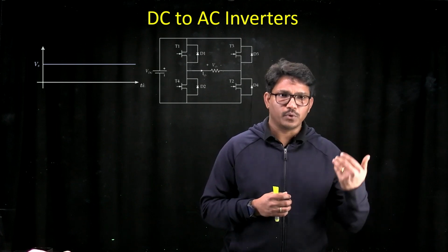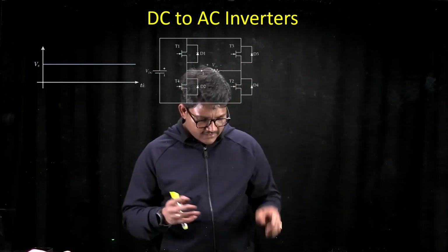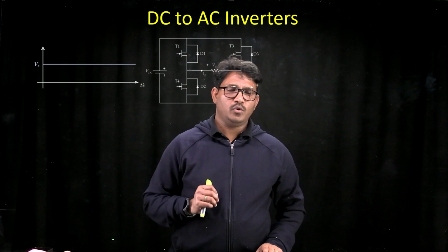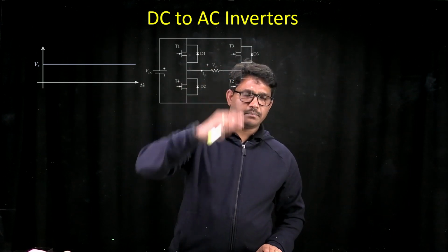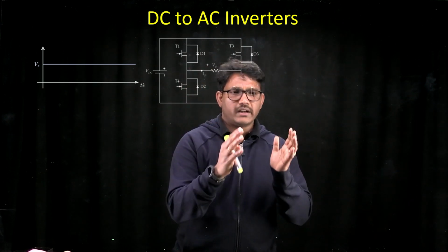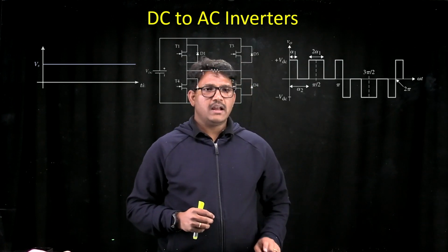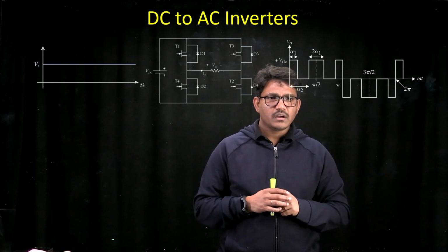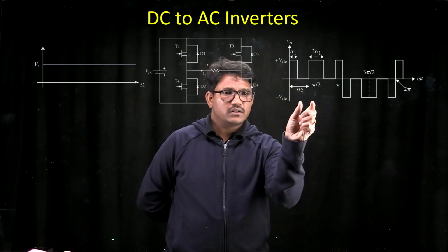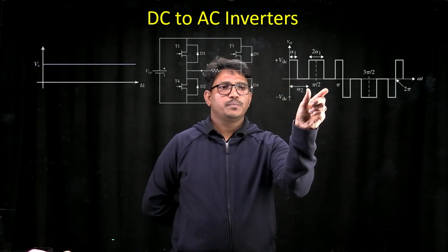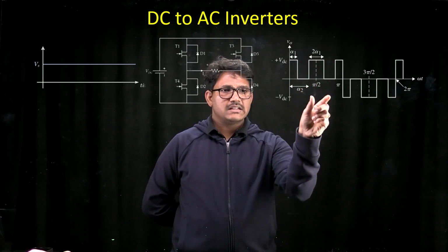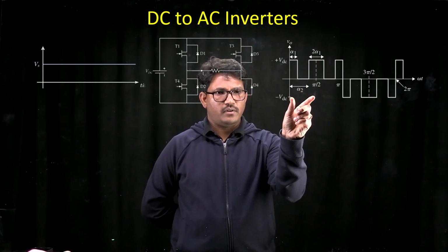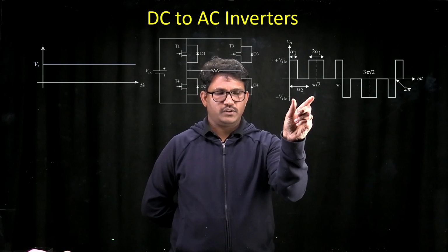of the output voltages? For example, you have an inverter where you controlled your switching periods and modulated your output voltage widths and achieved this particular output voltage waveform, where the width of this waveform is 2 alpha 1 and the starting point of this waveform's middle width is alpha 2.